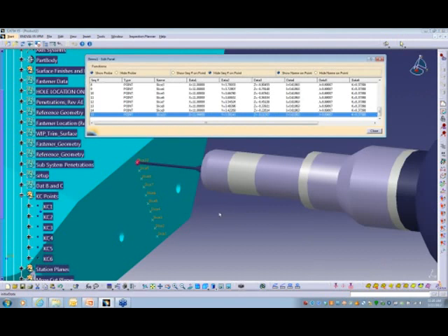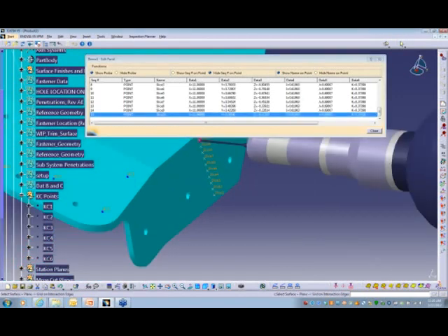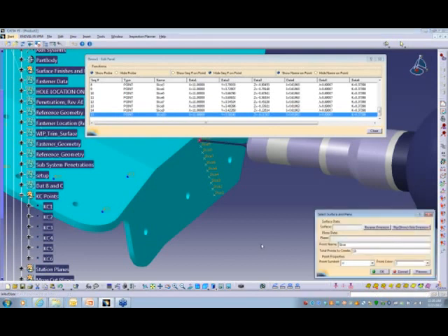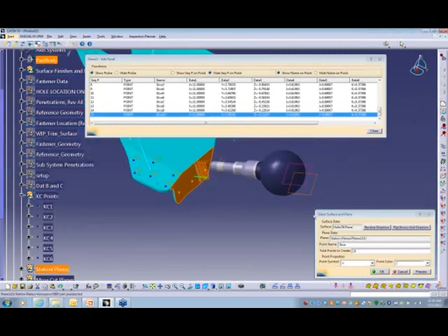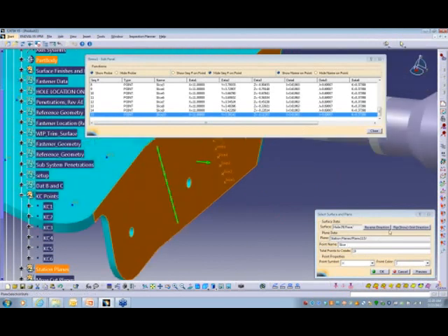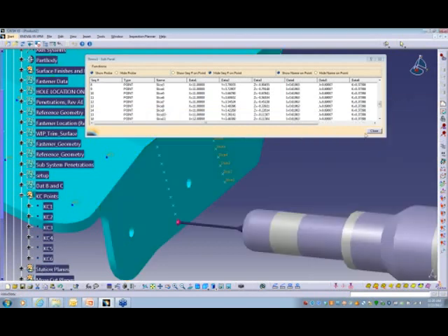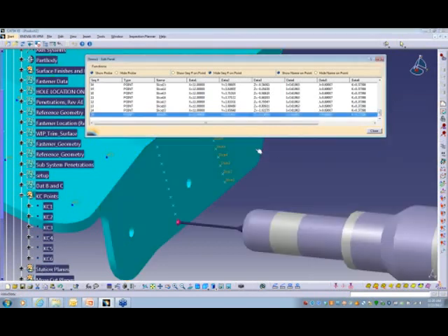So now those planes are called slice, and they can have any name you want. So we'll pick that again, and this is where that name is coming from. It can be any name that you want to have. We'll pick that surface, select the vector. This time we'll pick the other plane. We'll preview it, and they're still going up. We can reverse that, so now they're going up and then going back down. We'll say OK. The real big takeaway to this is you can see that these are exactly station points.